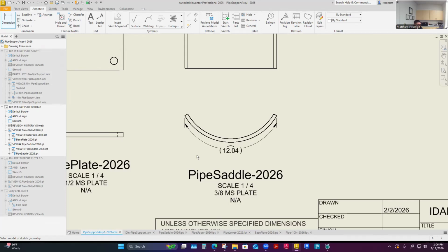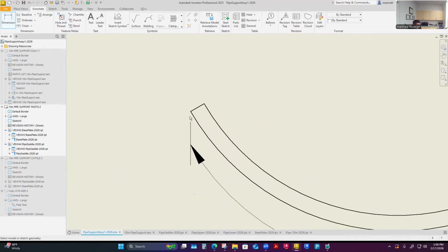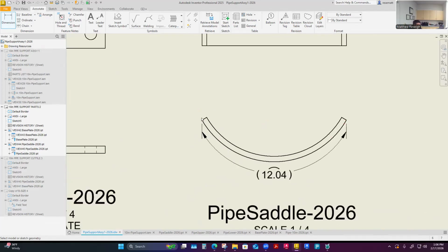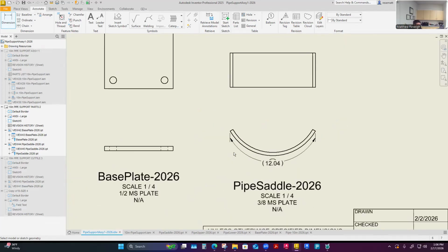part length. It's weird. If I put a measuring tape around the outside of this, it would measure potentially close to it. But this is what's confusing, and this is what confuses people that also work in sheet metal material or plate rolling, when we figure what we call the stretch out, which is how long of a part I need to cut to do what our part's doing. That's why flat pattern creation is really fast, because it just calculates that for us.